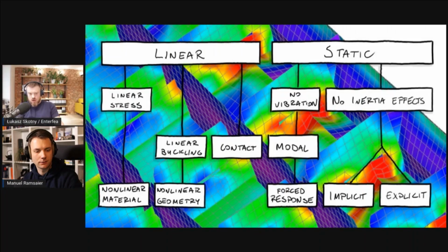The magic of imperfections is that you are using nonlinear geometry to predict, while you're running the analysis, if this load stops, and linear buckling just can't. So I think that in my experience, using imperfections in linear buckling is a futile exercise because it won't provide you with the information that you need, at the cost of extra labor. So you're not gaining anything really by doing this because it's still not a quote unquote correct answer. It's just a weird answer.